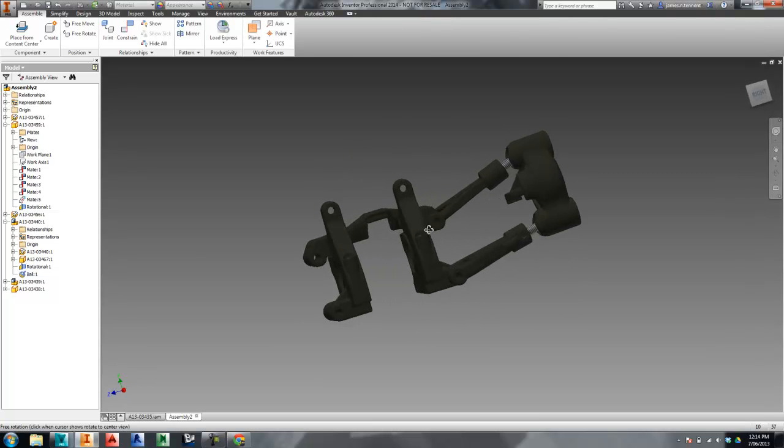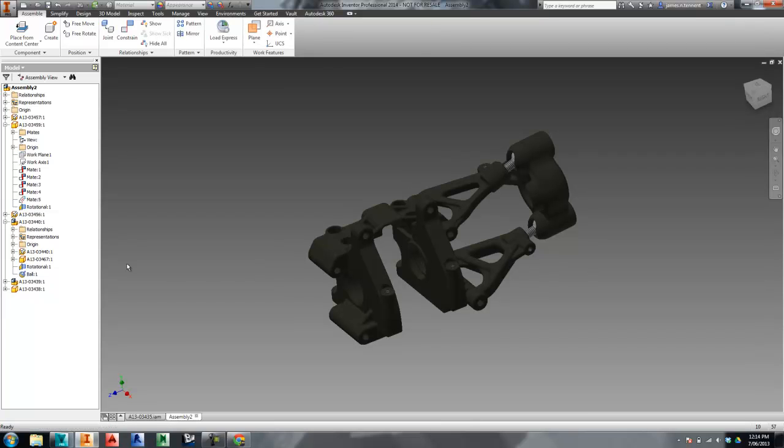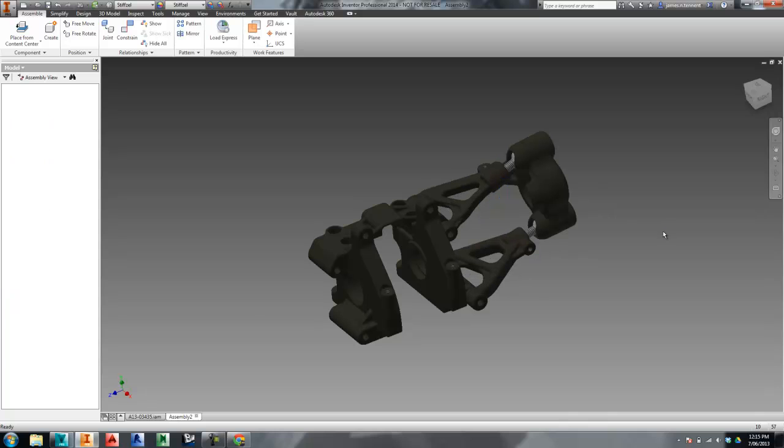Really nice way of doing your constraints, and as you can see, it's a very easy way of doing your constraints. You can also see in the bottom here, you can have a look at the constraints just like you would in Make Constraint and whatnot. If you need to, you can lock those constraints, and that will allow no degree of freedom on that, which locks that whole component. By unlocking it, you can go and do whatever else you need to do.